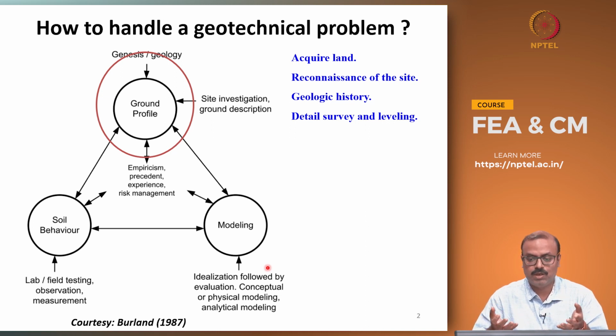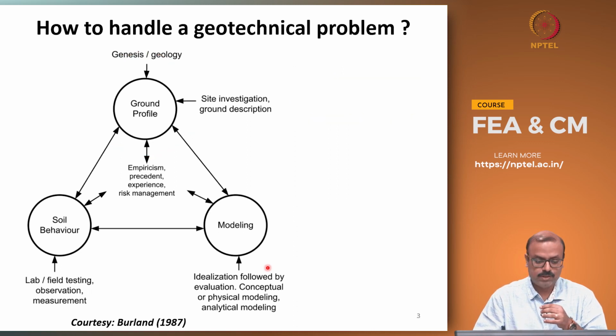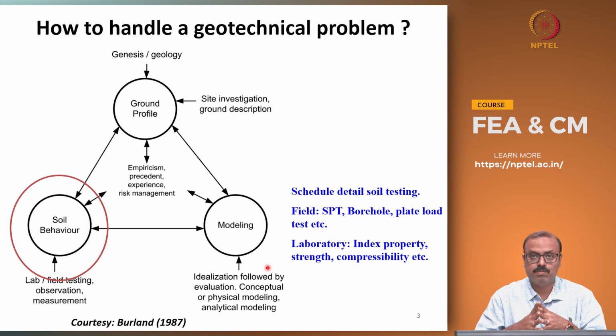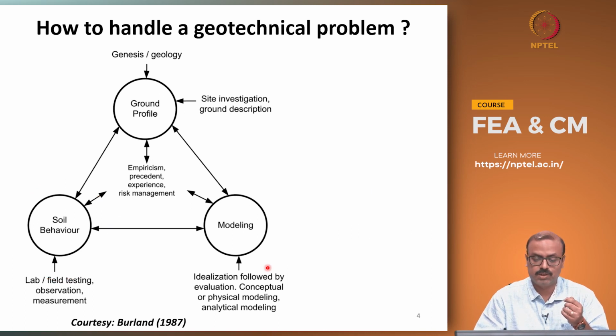So, you have to acquire land, then do reconnaissance of the site. You have to understand the geological history, the formations, then the detailed survey and the leveling. So, the overall genesis of the site has to be done. Then the next, very important step is how the soil behavior is happening, like what should be the ideal schedule for the soil testing, what are the different types of tests you should do, field or laboratory, in the entire spectrum of the soil investigation.